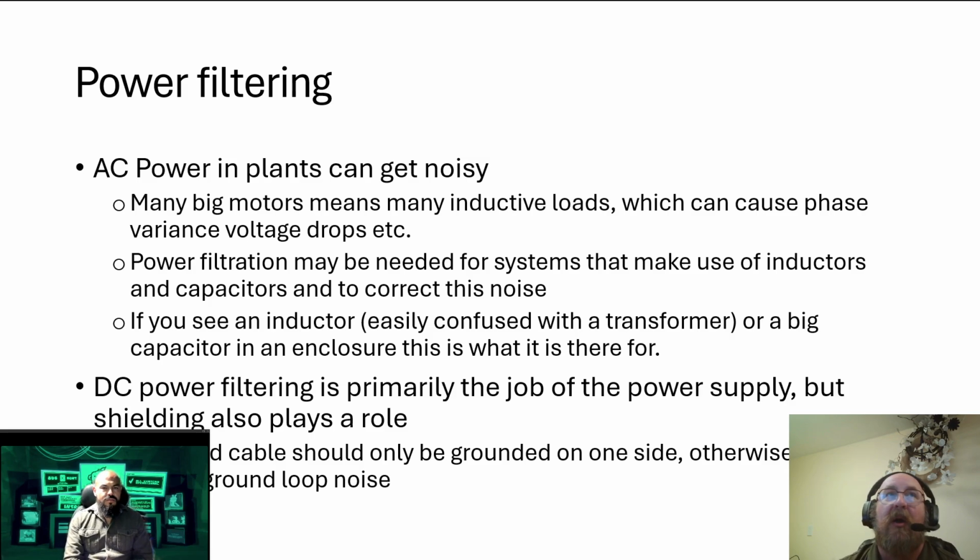So, AC power can get quite noisy when you've got all of these different inductive loads on things. Motors, when they're starting off, can cause phase variance, you can get voltage drops, etc. You'll learn a little bit more about these things as we get into RLC circuits a little later this quarter. And cleaning up that noise is important, especially since different equipment can become sensitive to certain amounts of noise. So you definitely want to filter that down for other sensitive equipment.